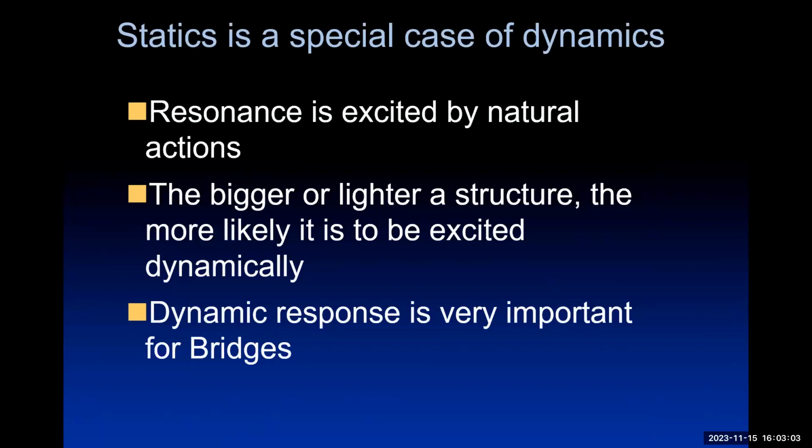So what we can say, though, is that statics is a special case of dynamics. It's simply a dynamic system in which we've told it that the frequency is 0. So resonance is excited by natural actions like winds or earthquakes. The bigger or lighter a structure is, the more likely it is to be excited dynamically, and that's because the damping is likely to be less as well.